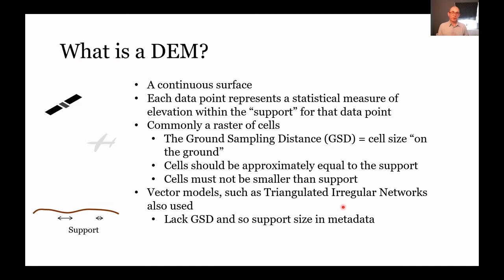We have information about elevation at all points where our model exists. But each data point, which is not the same thing as the surface itself, but each data point that has been measured is actually a collection of data. It's a statistical measure, as it says here, of a particular area, the support. We have an instrument that is making a measurement, or perhaps several instruments that are making measurements over a particular area, and they require a certain area over which they can gather data from.